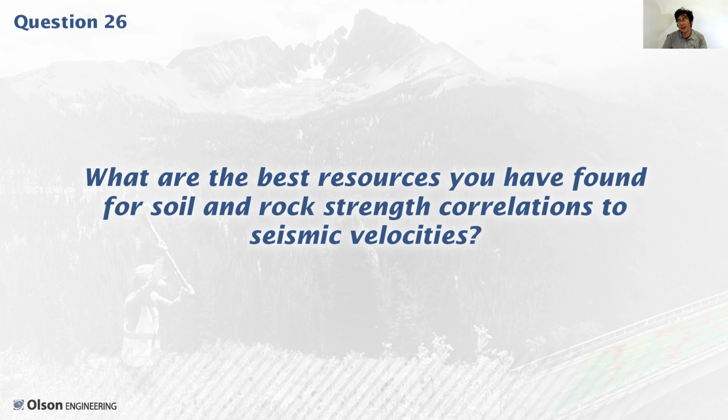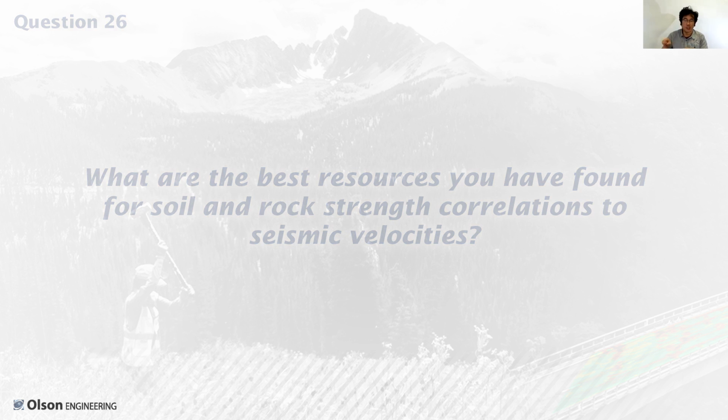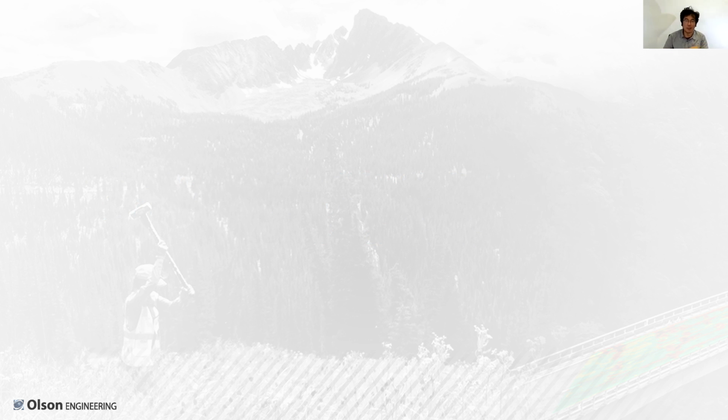That being said, shear wave velocity tends to be a little bit more interesting for soil and rock strength than P-wave velocity. So you might want to do a shear wave survey or a P-wave survey. These things will vary usually in conjunction with each other. So higher velocity, higher strength, but that's not always going to be universally the case.